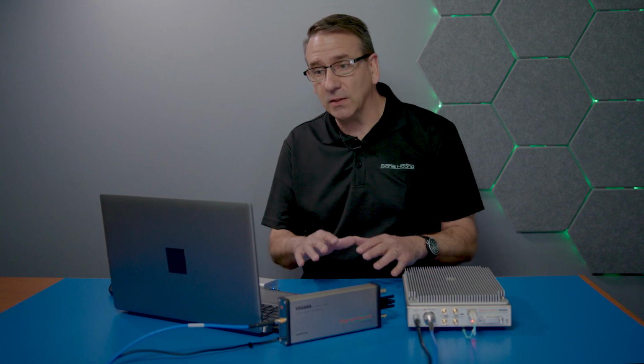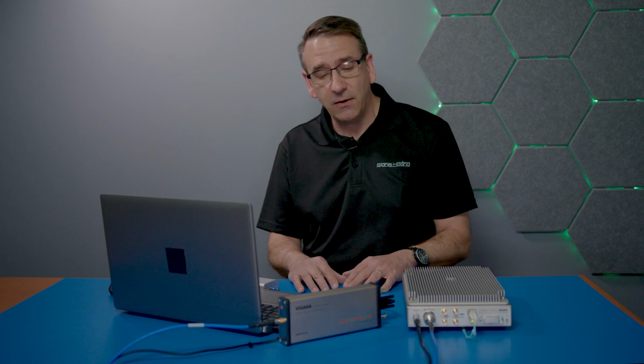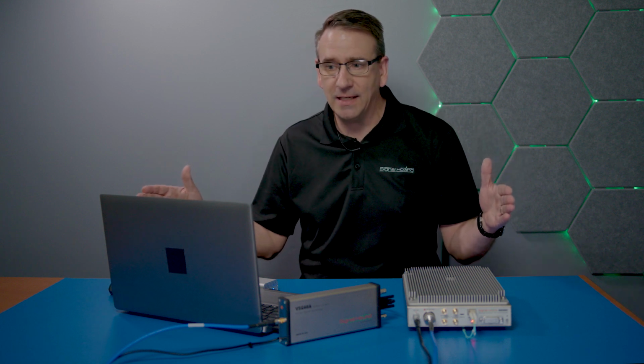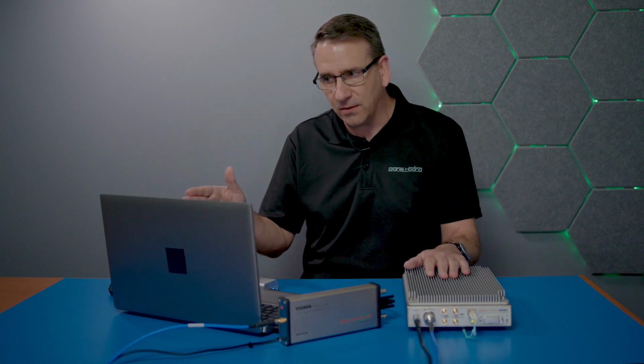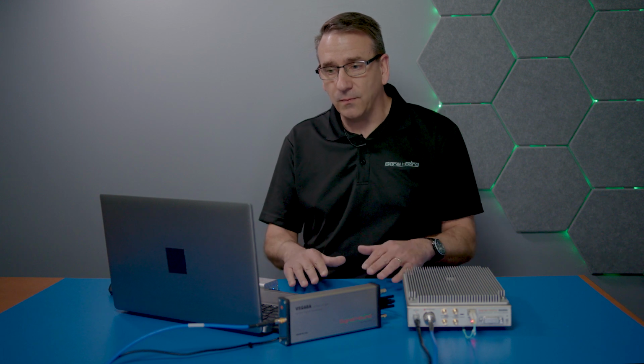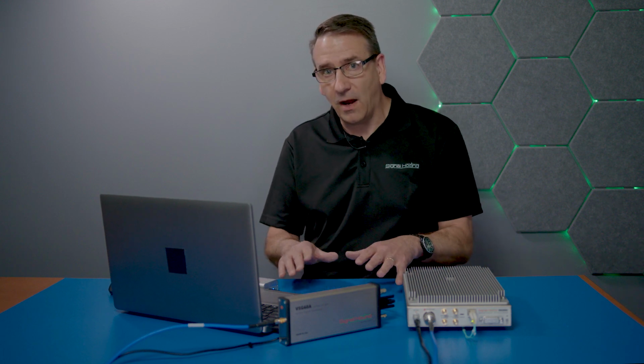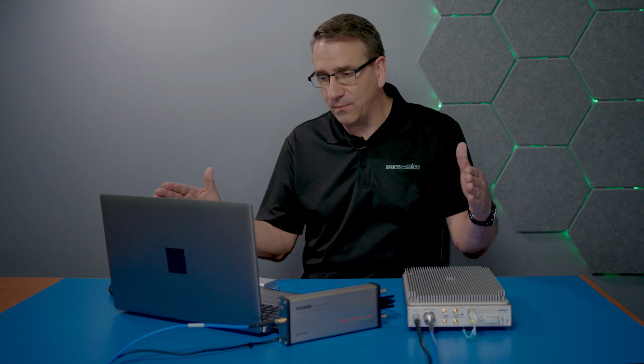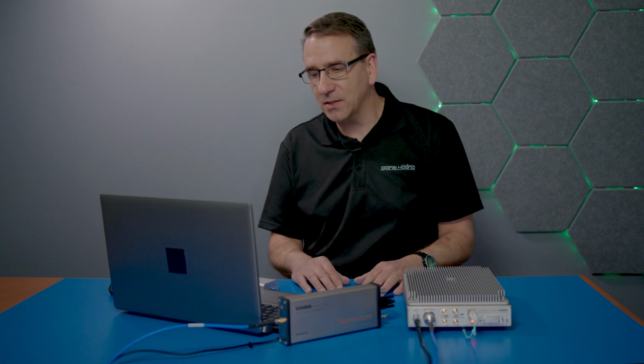And in Spike, when you launch it initially, it's going to go out and detect the device that you're connected to, the spectrum analyzer you're connected to, and it's going to determine the max full span width of that device, and it's going to set the center frequency for you, and it's going to enable what we refer to as auto triggering or a continuous trigger mode. And upon boot up, it's going to show you what the RF spectrum is as seen by that device through the span that is that device's entire span.